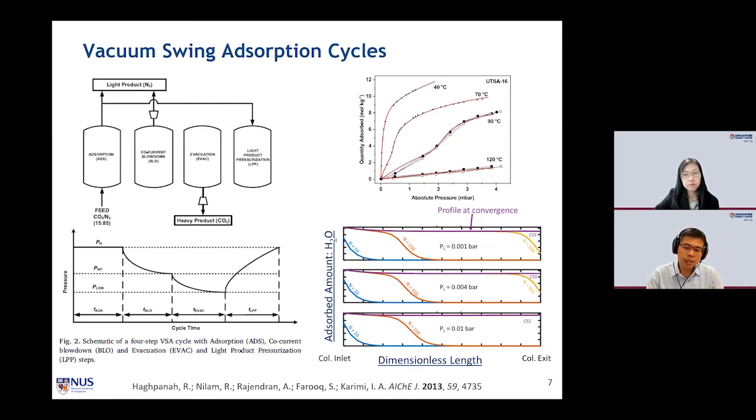In the real carbon capture process, if you're talking about adsorption, we mainly have 2 approaches. One is vacuum swing adsorption. So in vacuum swing adsorption, this is a column. So we'll fill the column with adsorbent materials, and we will introduce the feed gas towards one end of the column, and the feed gas will travel along the column. And when it travels, let's say if the feed gas contains only CO2 and nitrogen, CO2 has a strong interaction with the adsorbent materials packed inside the column. So you can imagine CO2 will travel slower, and the nitrogen will travel faster, okay?